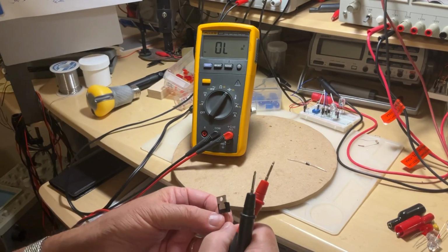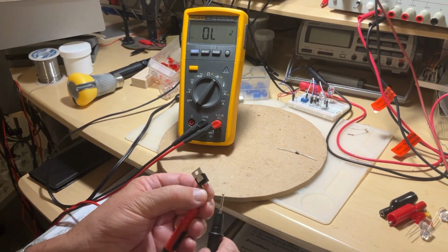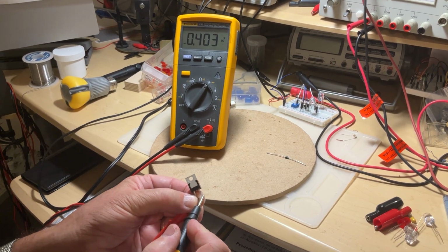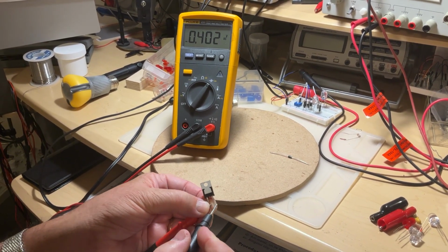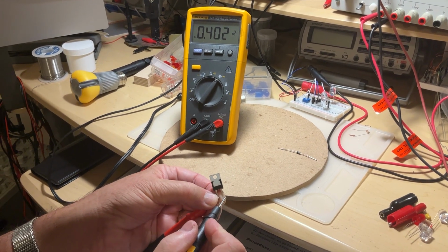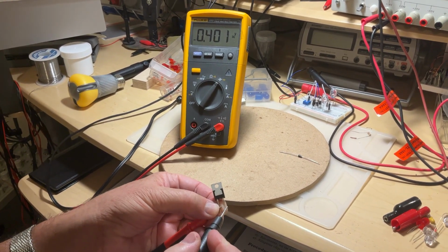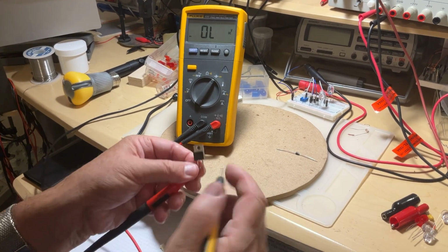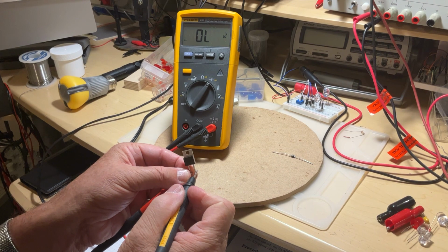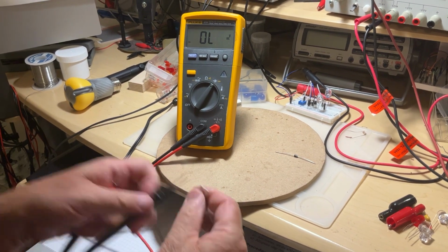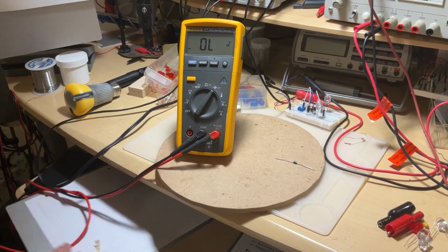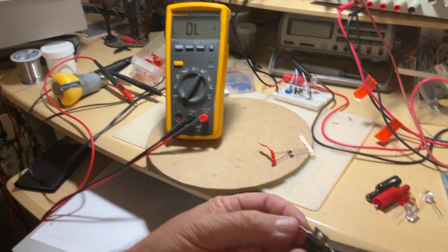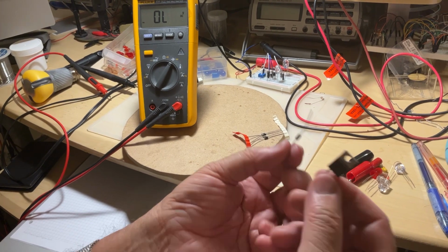This is a bigger diode. Let's suppose I don't know which of them is the anode, which of them is the cathode. It just happened I connected it in the conduction order. So the terminal on my left is the anode, the one on my right is the cathode. If I put it the opposite way, like this, it won't conduct. Open circuit. But again, what do you notice? You notice that the body of both diodes is an opaque body. They don't emit any light.